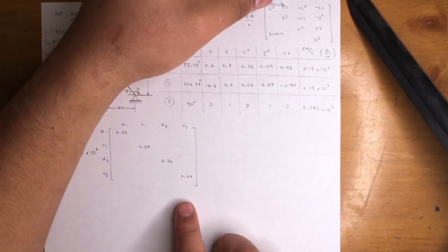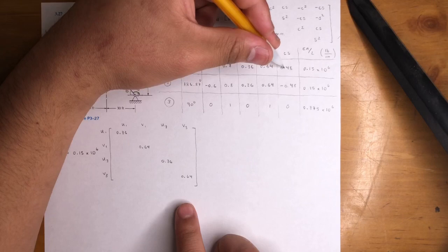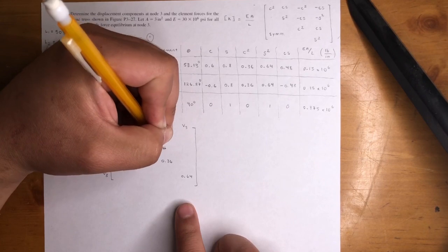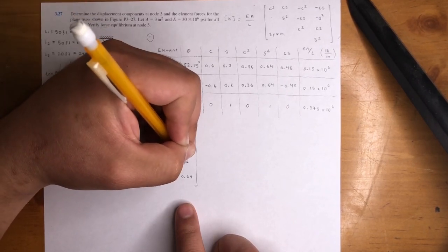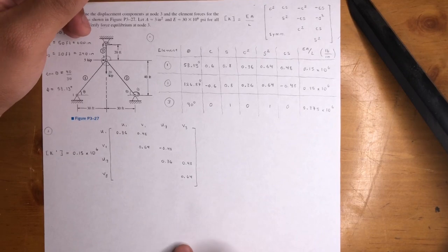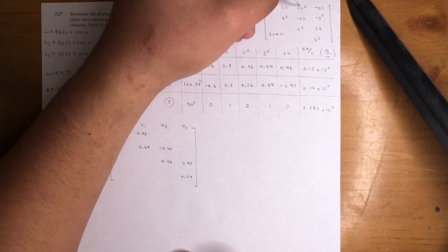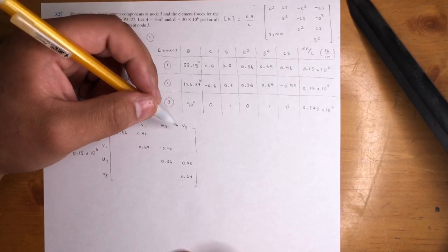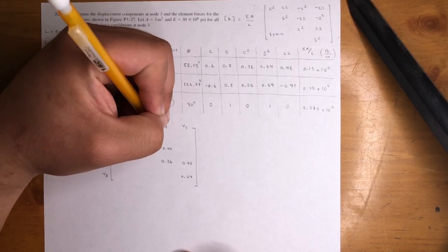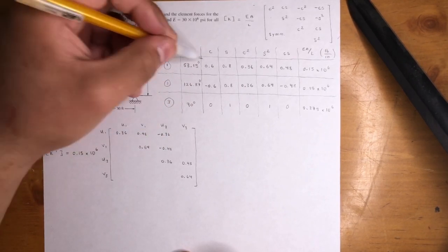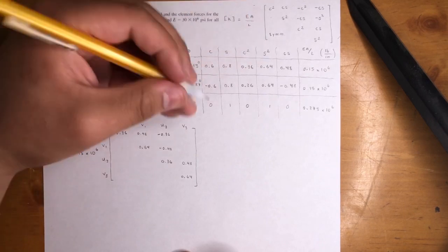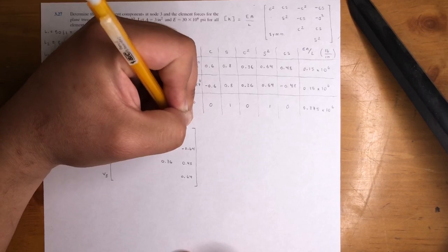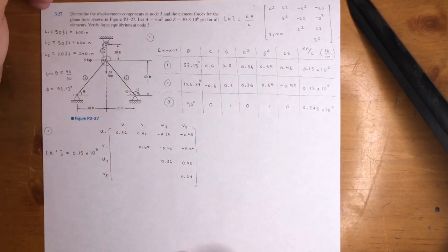Then cosine times sine, negative, and then positive. So it's this number, just positive, negative, positive. So 0.48, negative 0.48, and 0.48. For U3 and V3, right here, negative cosine squared, negative sine squared, my bad. Negative cosine squared, all right, so it's negative 0.36. Again, we're looking at the first element, so these 3 numbers right here. And then negative 0.64, and then finally a negative cosine sine, which is negative 0.48.